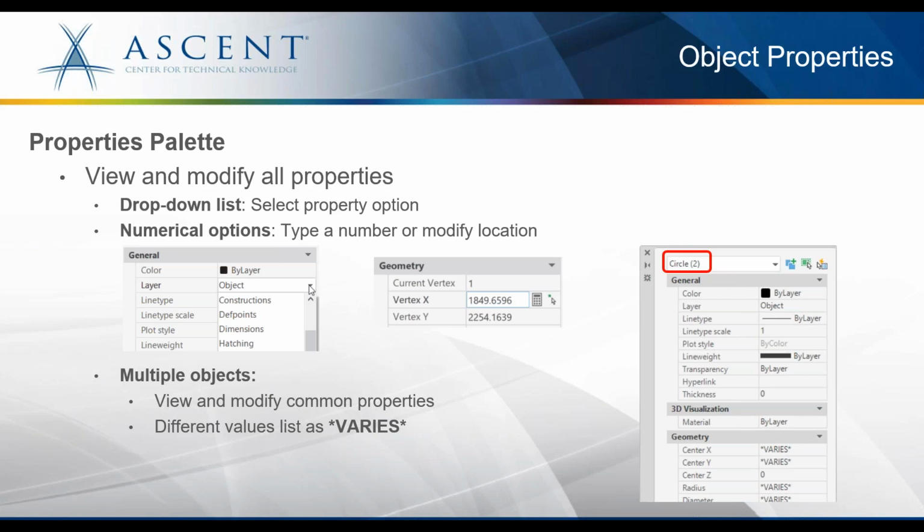The multiple selection is useful when you have to change the common properties for all the selected objects at the same time. For example, if you have several circles in a drawing and you want all of them to be of the same size, what do you do? In that case, you will select all the circles and change their radius to a certain radius in one step, and it will get changed for all of the selected circles.